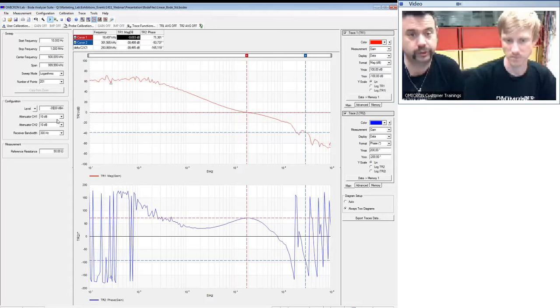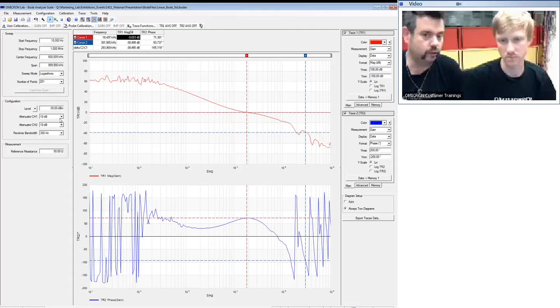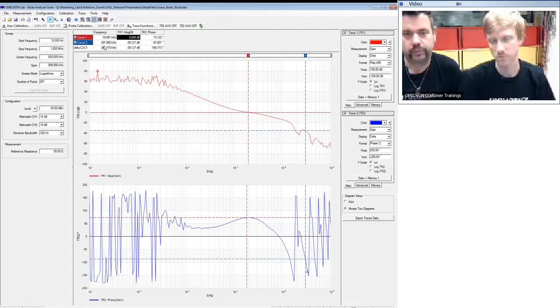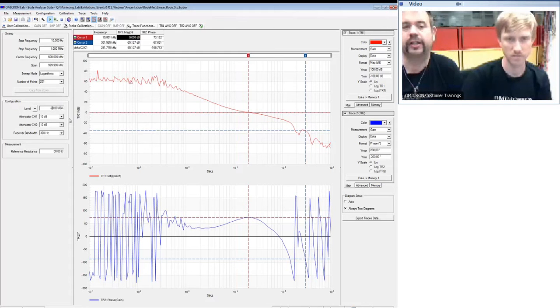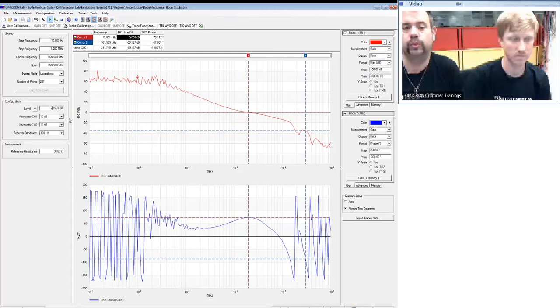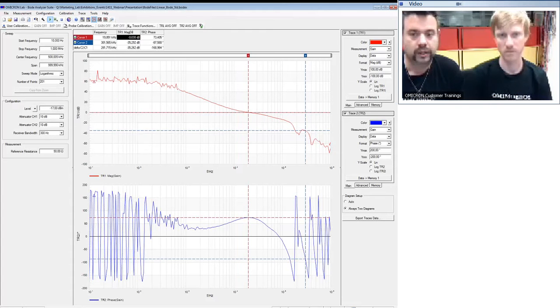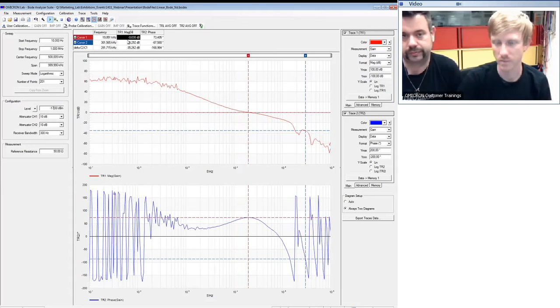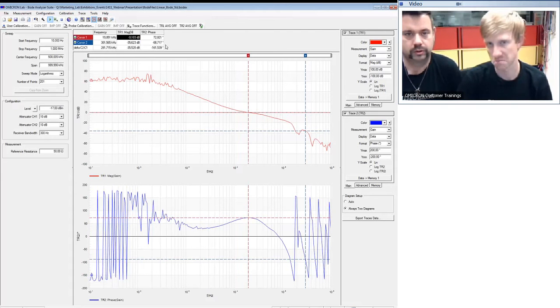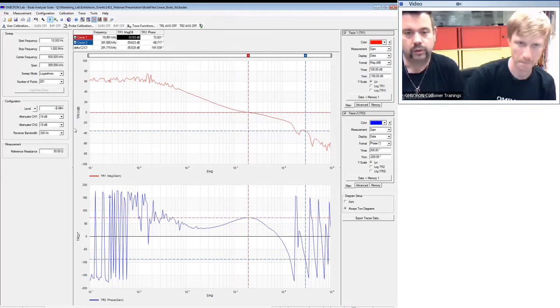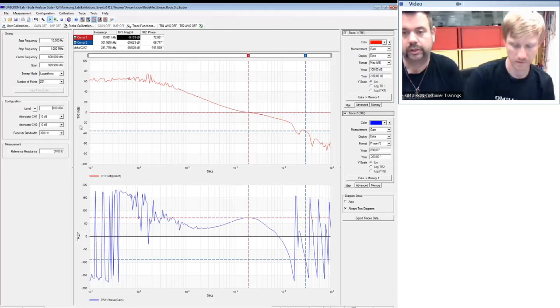The noise is getting more, especially at the low frequencies. But now we see that the point has only slightly moved. And a rule of thumb is, you reduce your level in 10 dB steps, and as soon as you are able to add 3 dB again, so for example, go to -17, and it's not changing, then you're making a correct measurement. So let's wait until the sweep crosses the crossover frequency, okay. And it is actually not changing anymore. Okay, so please go back to -20. Now we are able to measure the phase margin.